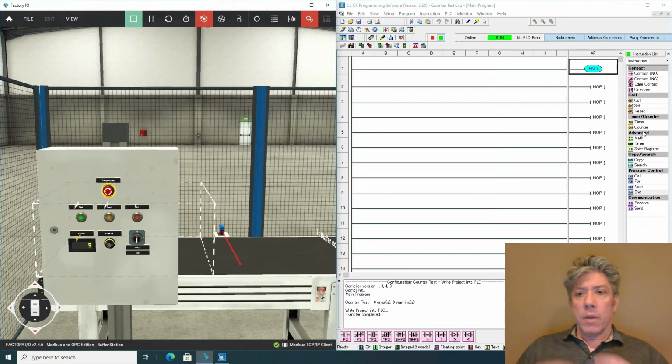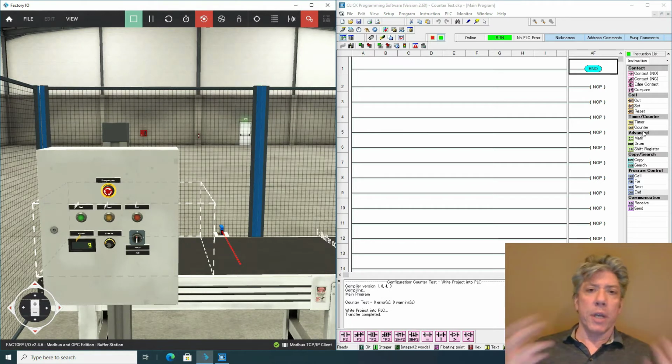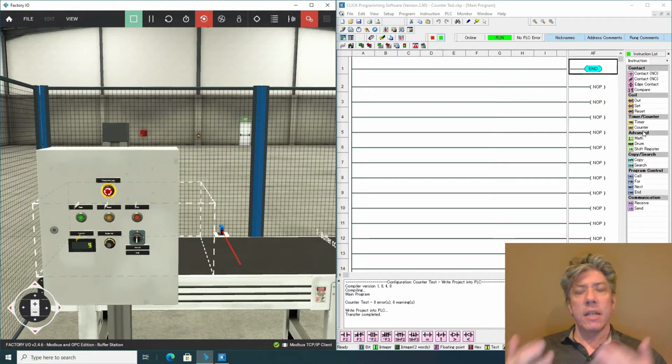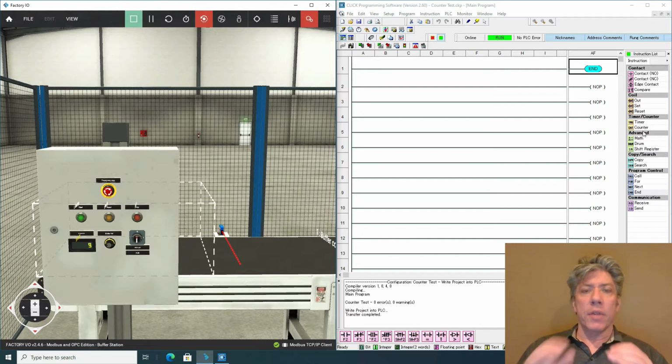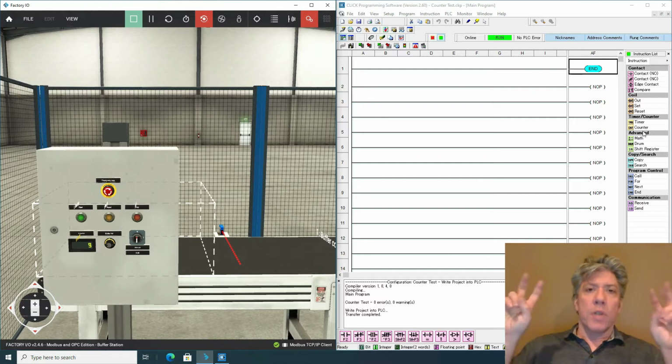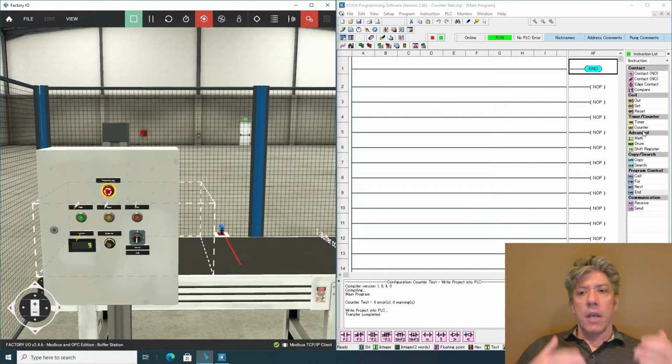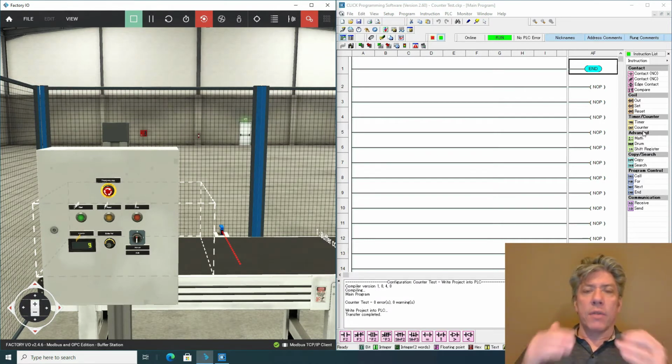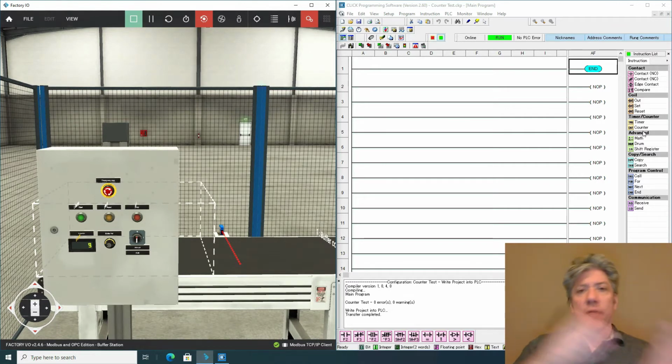So in a timer and a counter, you often have what's called a preset value. And sometimes you care about that value, sometimes you don't. But the idea is that this value is the amount that the timer or counter will go up to before it is done. Now, sometimes a timer will shut off or a counter will count no more. Most PLCs, that's not the case. In most PLCs, after the timer accumulated value has reached the preset value, in other words, after enough time has gone by, it's kind of like setting an alarm.